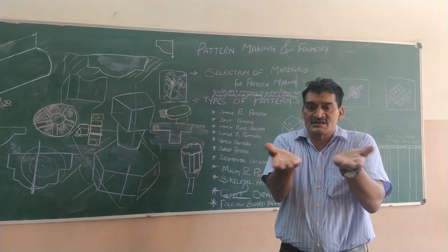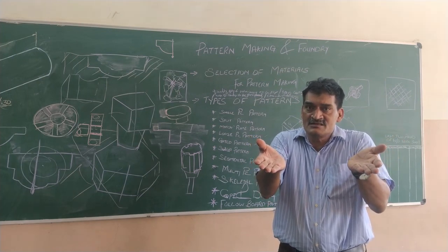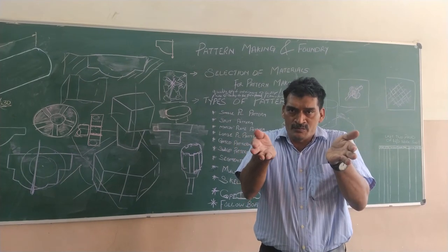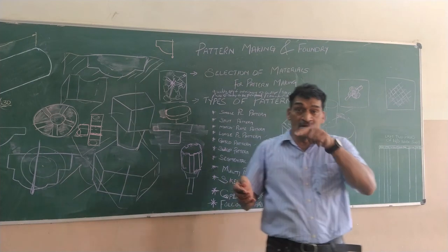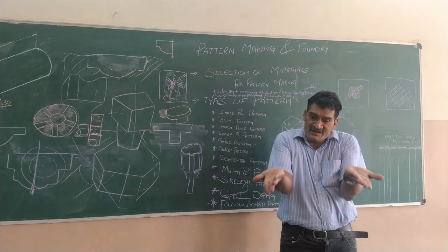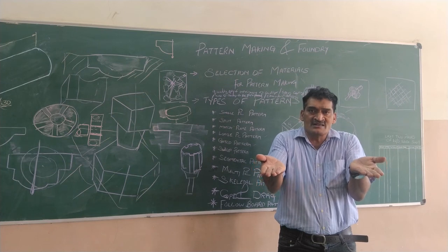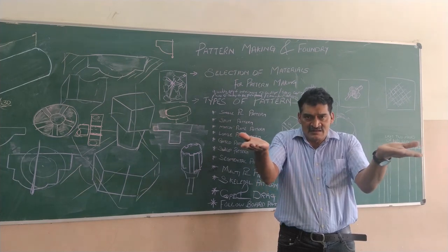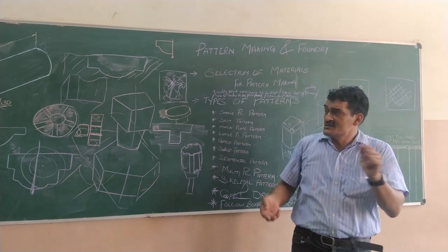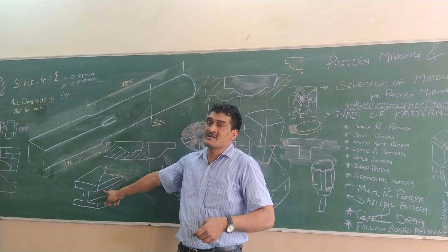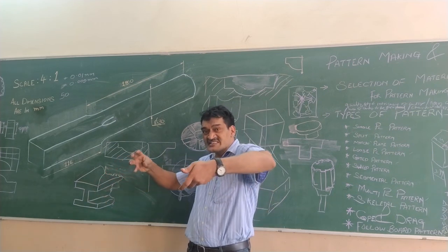As the casting cools, it will tend to warp in the upward direction. So what we do is, on the pattern, we bend it in the opposite direction so that on cooling, it forms a somewhat flat surface. Similarly, if you see, when we have I-beams like these, they tend to contort or twist.